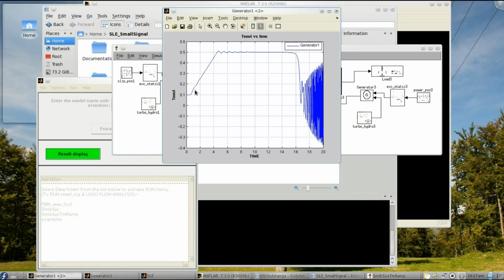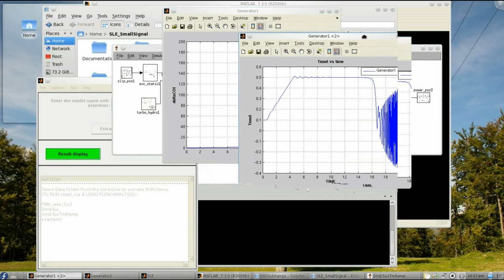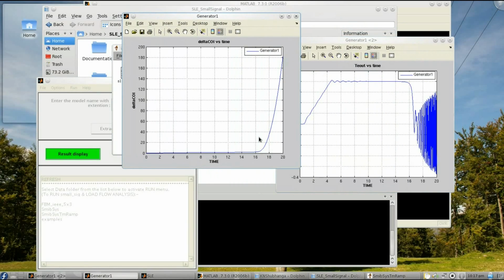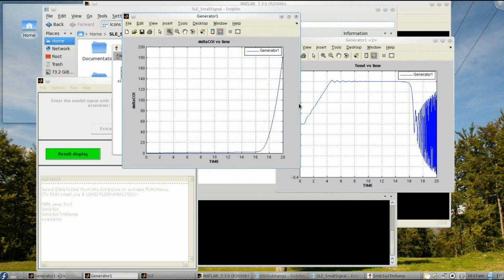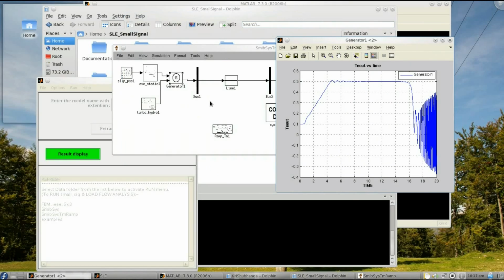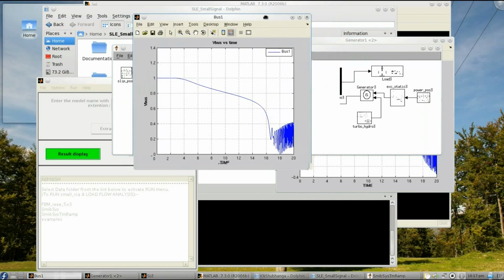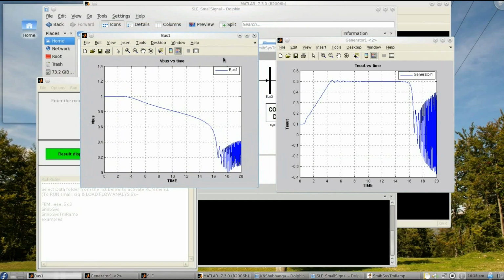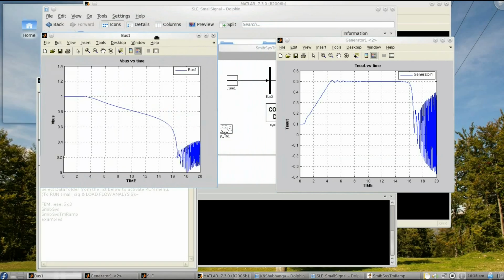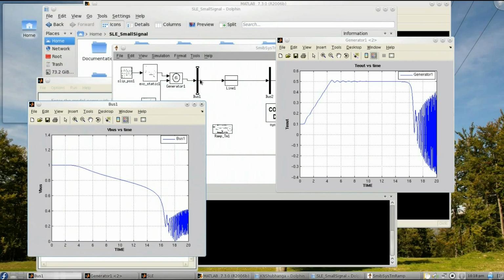There we have. So the electrical power is having some oscillations, which we term as an unstable case, loss of synchronism we refer to as. It is clearly observed by the delta excursions taking place. It is monotonically increasing. A similar effect can be observed in the bus voltage trajectory. So it crosses the limiting value of voltage. So if we have an automatic excitation controller, then this voltage can be held and the stability could have been maintained.